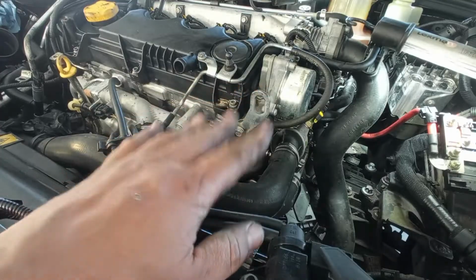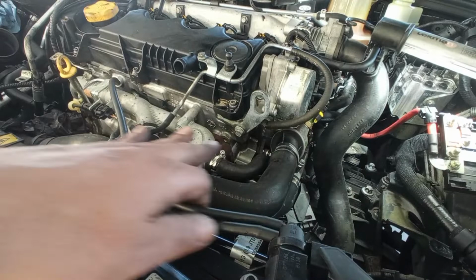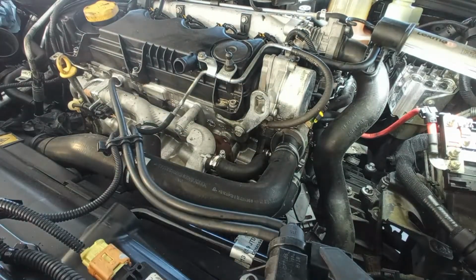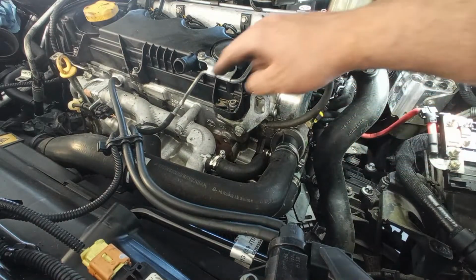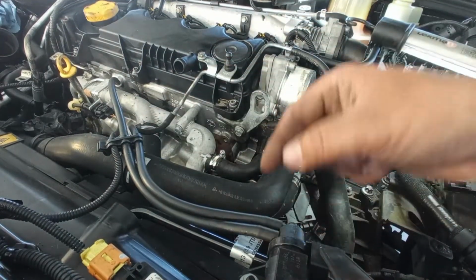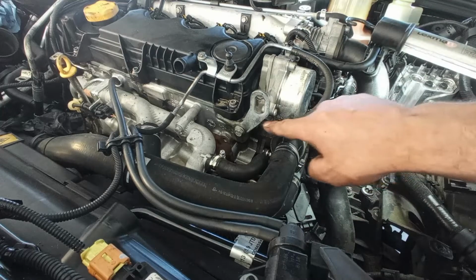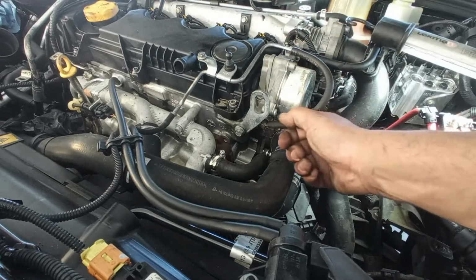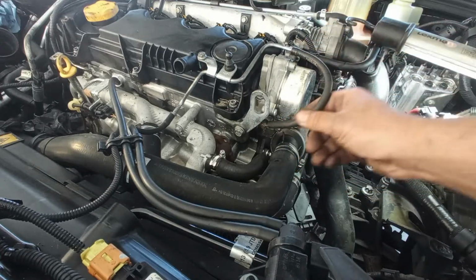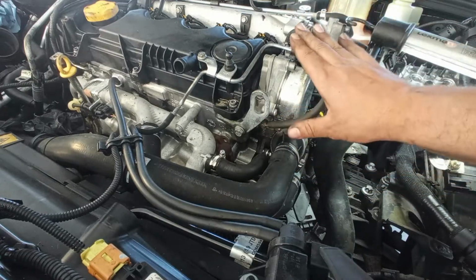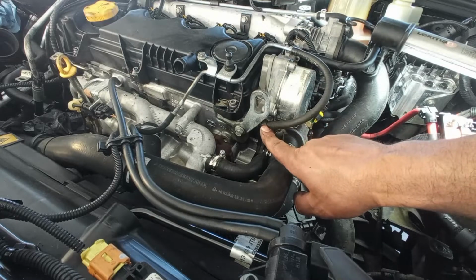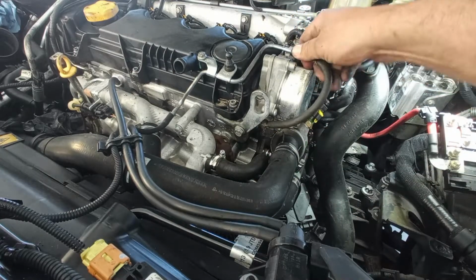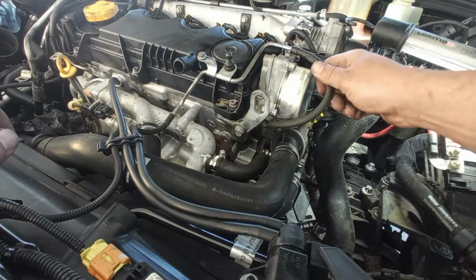The next thing that is failing is this vacuum control for the position of the turbo, for the geometry. You have this feeding over here for the vacuum of this regulator, of this solenoid. This hose right here was with so much oil that it was completely loose. This one is already a new one, okay? Very difficult to put in because you have here 4 millimeters and you have here 5 or 6. So the hose has to stretch a little bit and it is very difficult to put in.